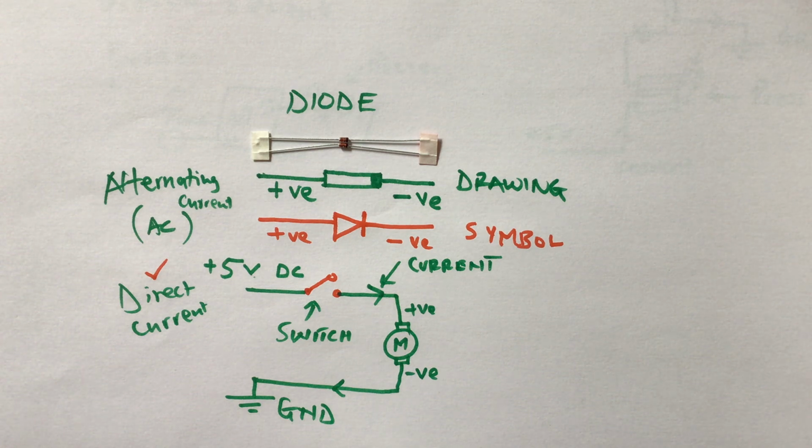So in this case, when we stop the circuit and the motor is still rotating, it becomes something like a turbine. And while it rotates, trying to stop, it gives out that small power. That small power is bad.